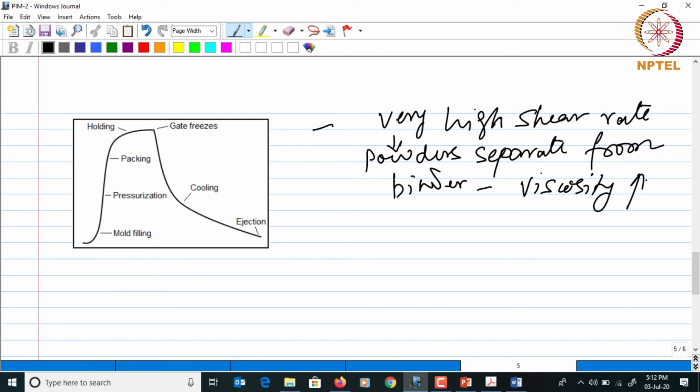Okay, so in order to make sure that the mold is properly filled, the pressure has to be held. First, it has to be continuously increased, as you could see from here, and we have discussed that before also. So if you see the pressure with respect to time, it has to be continuously increased as the mold filling starts.